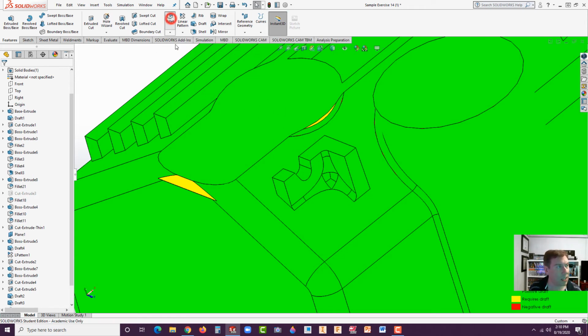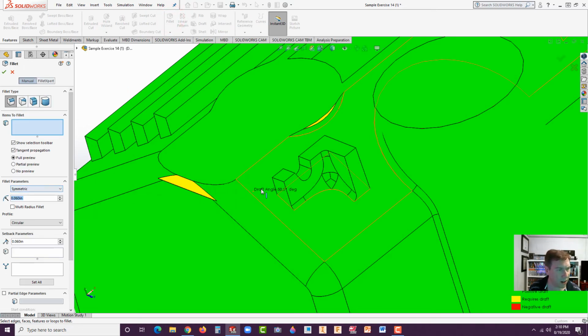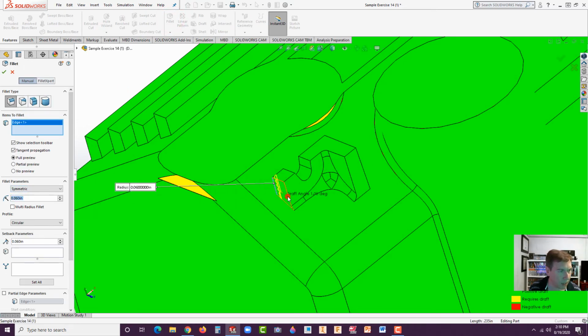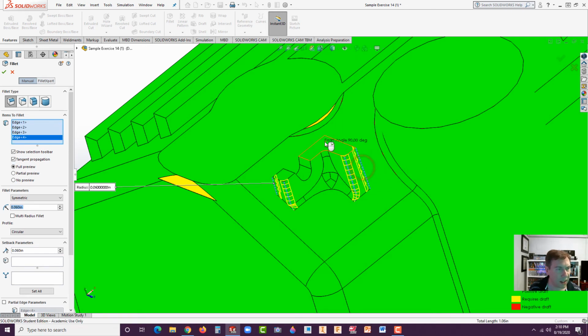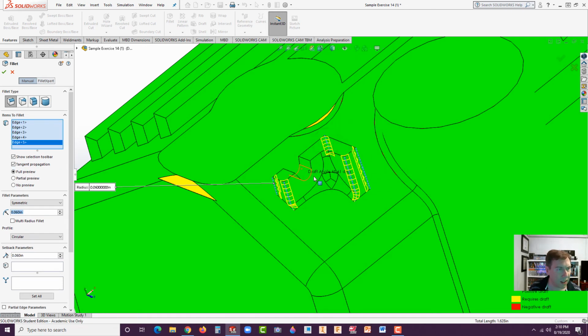All right, let's go to fillet. And filleting is really an art. It can be quite tricky at times. And it's all about order. And sometimes you just can't put a fillet in certain areas. And what we would do when I worked in industry, we would note that in a drawing, and we would let them put it in manually. Either they could put it in the CAM software with surfaces. You could probably do it in here too. You usually could get it to work if it's real geometry.